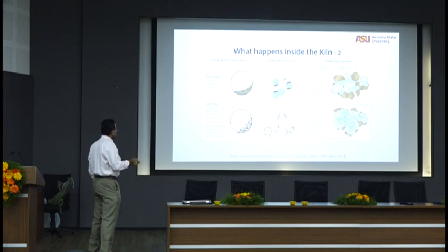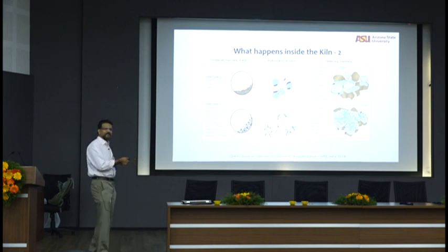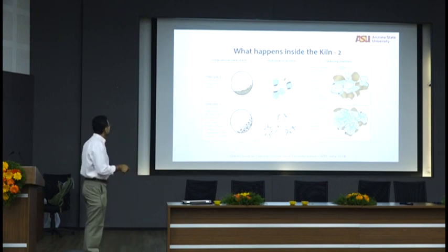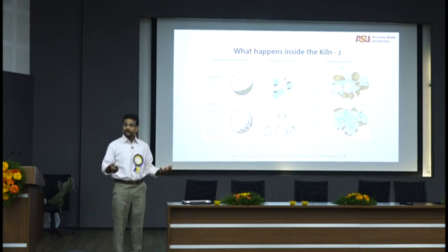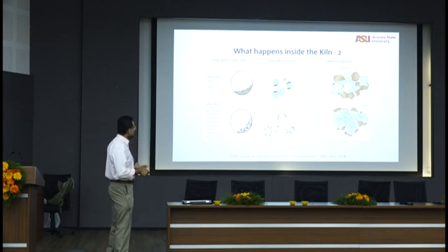Now, at higher temperatures, you start to have sticky particles, reactions between solid particles will start to happen. Small B-lite crystals, B-lite again is C2S, A-lite is C3S, B-lite is C2S. B-lite crystals form from combination of silicates and CaO. Free CaO starts to go down. 1200 to 1350, more agglomeration, capillary force keeping the liquid together. About 1250 Celsius, a liquid phase is formed because now you have melting that's happening, right? And what do you have in that liquid phase? C3A and C4AF. They happen in the liquid phase, and that liquid allows the reaction.